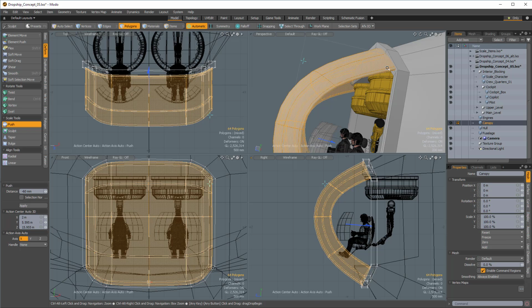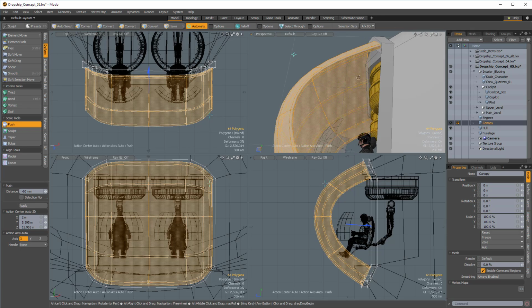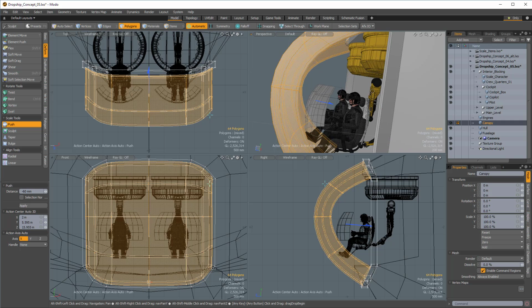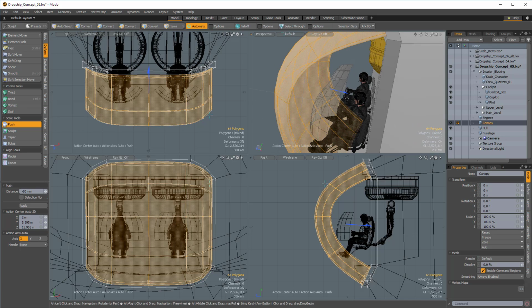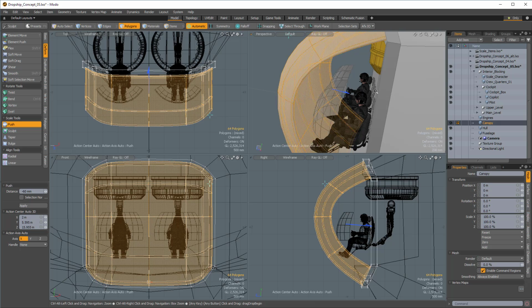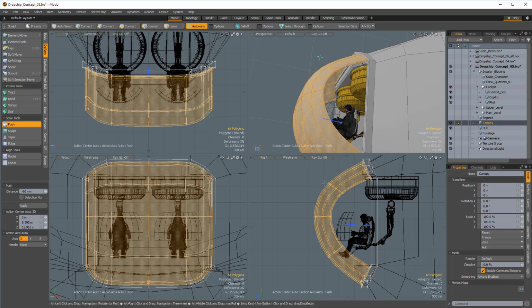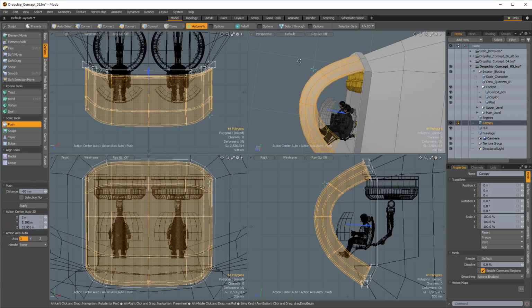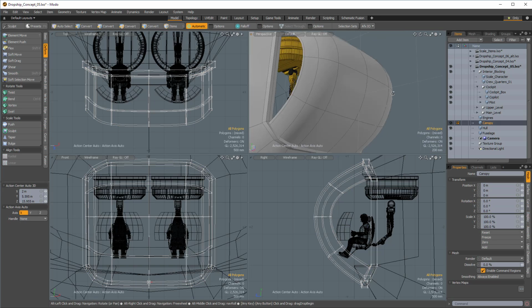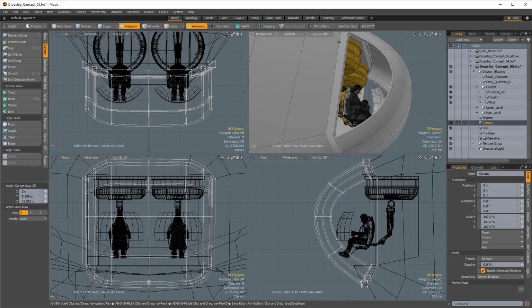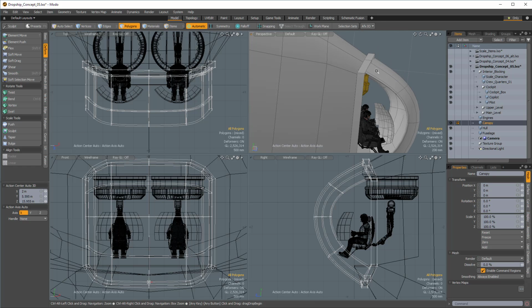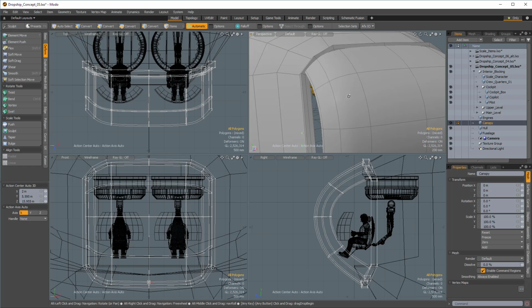We're going at 200 millimeters across, which is pretty thick for glass. So by pushing this in, let's go down. I don't want to go too far because this is pushing from both directions. So I'm going to go down, I think 60 millimeters is pretty good. That's going to still leave me with 80 millimeter thick glass, which is pretty thick glass. It should definitely look bulletproof. All right, so that's going to work for there.